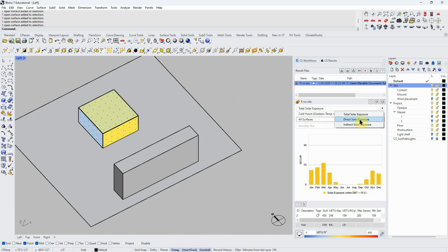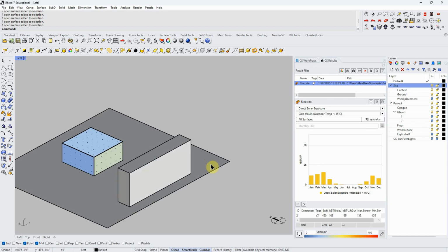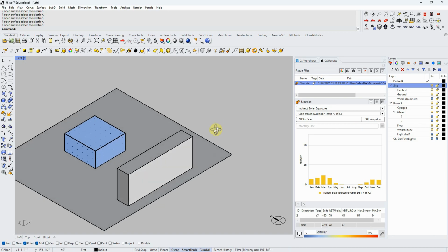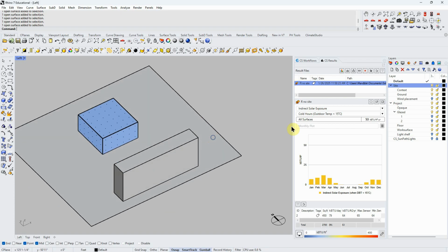So direct, remember, is direct normal, and so it's basically the idea that if the surface were pointing directly at the sun with no clouds, how much sun would be hitting it. And then indirect is the amount bouncing off of clouds. So if we're in a climate that has more clouds, we're going to have more indirect than in one that doesn't have clouds. This is one simple way of summarizing it.